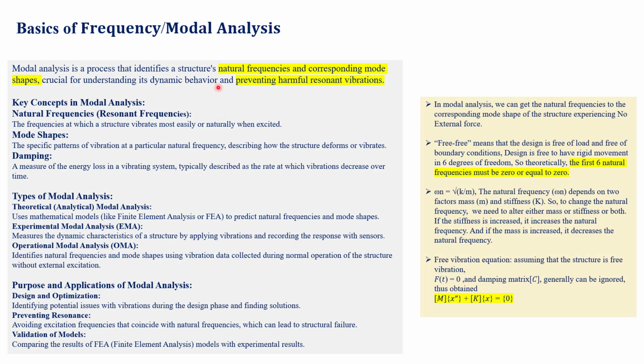So next, when it comes to modal analysis, we have the free analysis and the forced modal analysis, where we add additional stress, like we force the model with the load cases, and then we extract the mode shapes. Yeah. So now we'll consider free. What exactly it does is it will be free, and there won't be any boundary conditions for this.